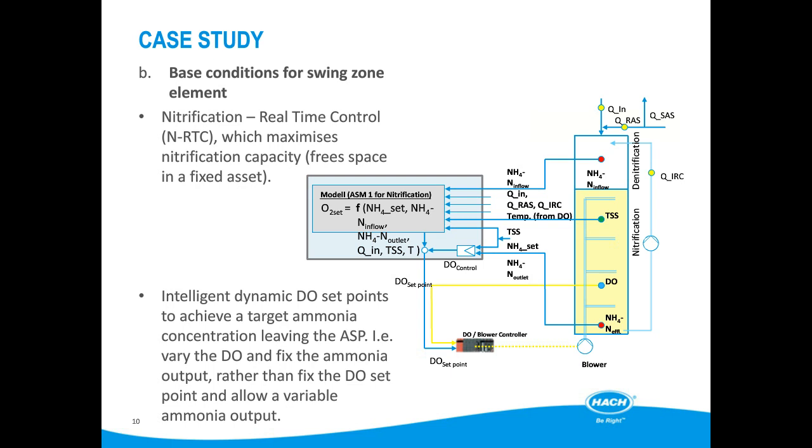The ability to lift all the DO set points during times of high load really does improve the actual treatment capacity of any ASP, and was particularly important for this application.